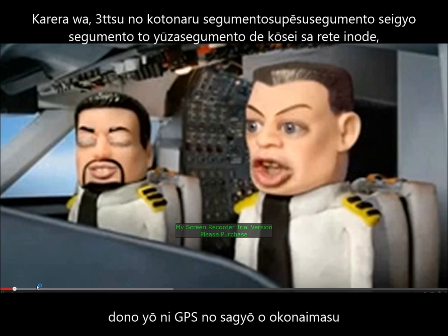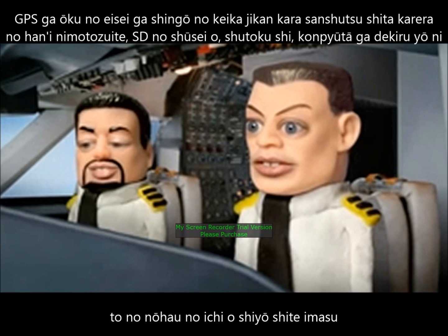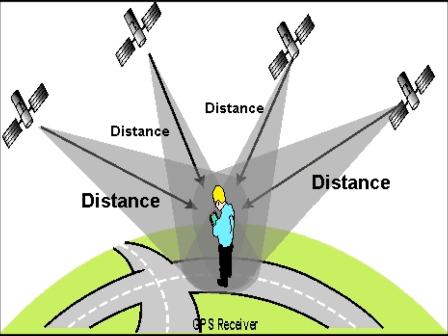So how does the GPS work? The GPS uses the known position of as many satellites as it can acquire, and then computes a fix based on their range, calculated from the elapsed time of the signal. The receivers compute a possible time error, and immediately begin a trimming process until it arrives at the answer, which allows all ranges to arrive at one and only one position.